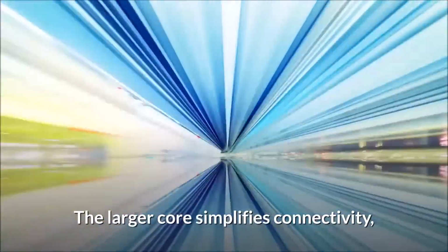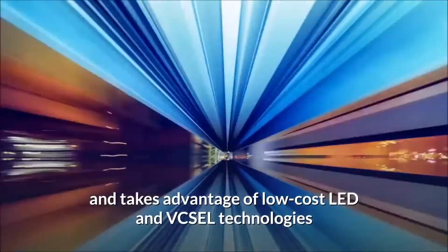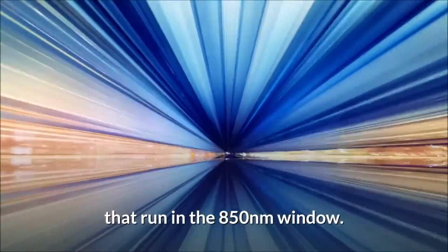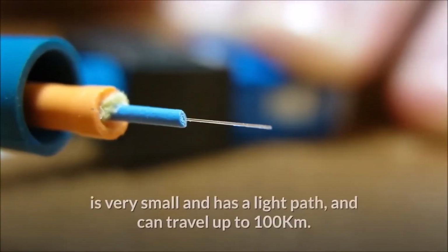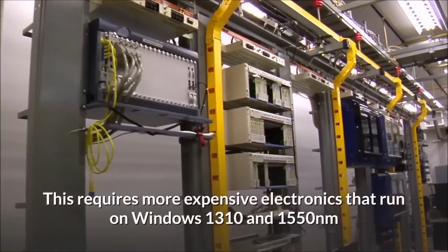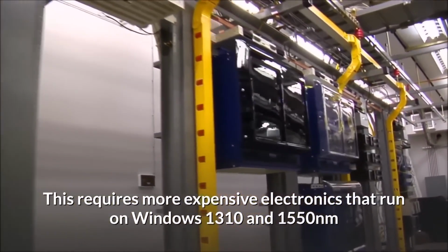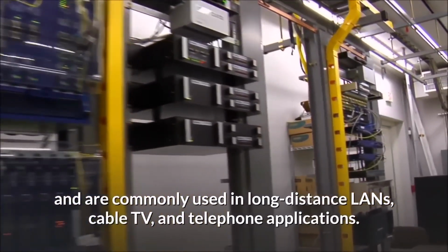The larger core simplifies connectivity, and takes advantage of low-cost LED and VCSEL technologies that run in the 850 nanometer window. The single-mode fiber has a core size of 9 microns, is very small and has a single light path, and can travel up to 100 kilometers. This requires more expensive electronics that run in the 1310 and 1550 nanometer windows and are commonly used in long-distance LANs, cable TV, and telephone applications.